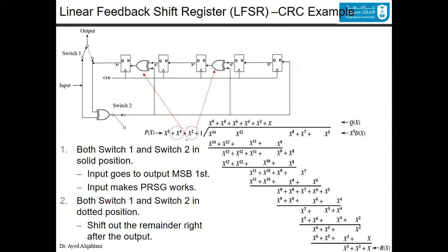The first information it gives you is the number of bits, the number of flip-flops that you have. So here it's 5. Since the maximum power is 5, there will be 1, 2, 3, 4, and 5. Now the 1 here and the x to the power of 5 give you the edges of your design. That's the first one, and that's the fifth. These are the flip-flops.